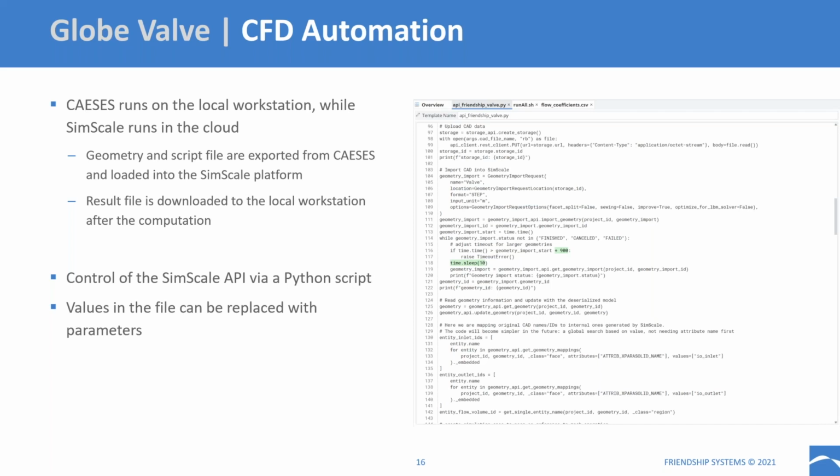And basically, this script is set up once at the beginning to have all the computation set up for our case. And then we're basically just using the same Python script for every variant that we're generating. So we repeat the whole process of assigning all the settings, running meshing, running computation, extracting results in the same way for each variant.